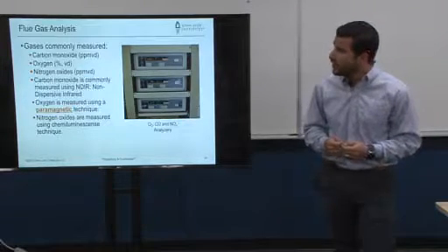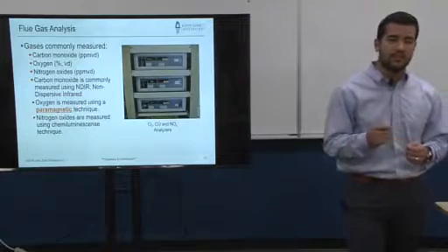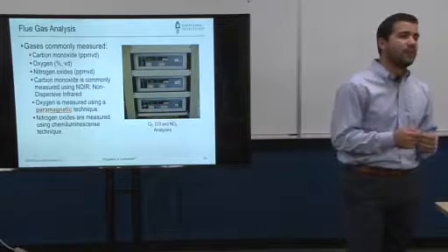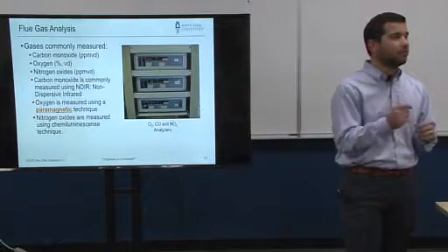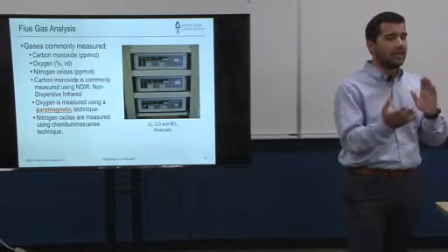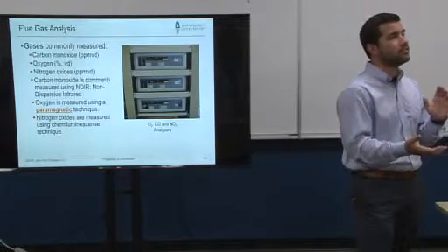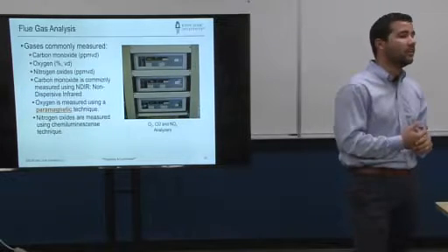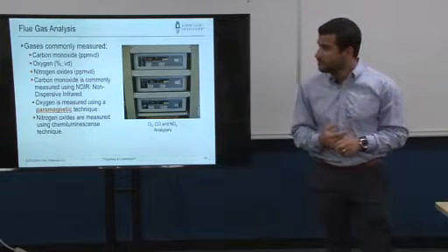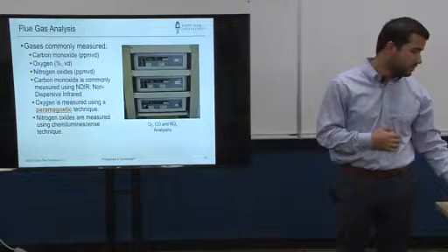And then finally, O2 is measured by inducing a magnetic field. So oxygen is actually paramagnetic, and what that means is it will react with a magnetic field. And when you do that, and so you have a stream of fuel, you make a magnetic field, and that'll create a pressure difference in that flow field. If you measure the intensity of that pressure difference, then you'll have an understanding of the O2 inside that stream. And that's how we measured those particular 3 components.